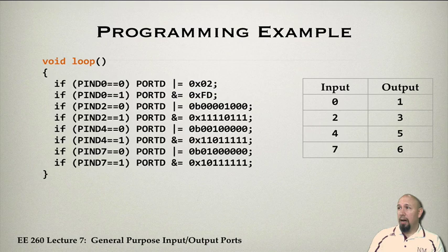So that's what we have in this particular programming example. So you can see exactly what's happening in this. I check a pin, and I do something with it. And the fact that I can actually check individual pins is like doing a digital read, and this is like doing a digital write. Okay, so when I do this, I'm actually doing a digital read, but I'm doing it much more efficiently than the Arduino command digitalRead does. It may be possible to make this even more efficient. I'm not sure how, but this approach works. Okay, so there's our programming example.